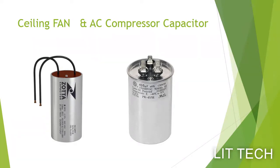Dual-run capacitors are commonly used in HVAC, heating, ventilation, and air conditioning units. Dual capacitors have 3 terminals, unlike regular run capacitors, which have only 2. Electrically, they are the same as run capacitors that have 2 terminals. Using a dual-run capacitor allows you to save space if you have a small mounting area.